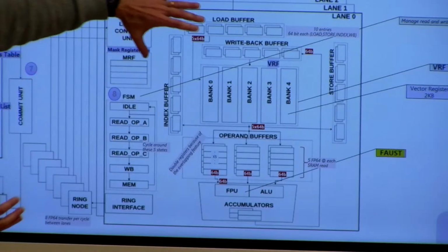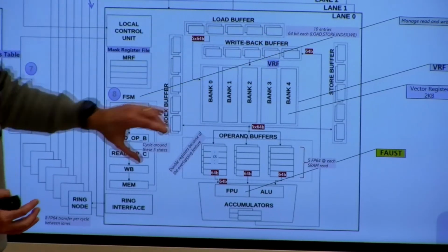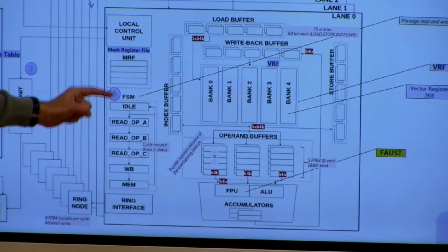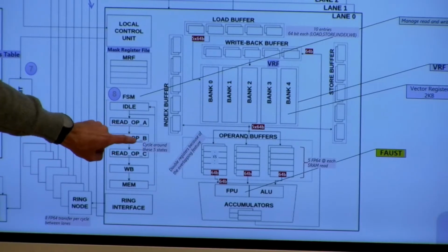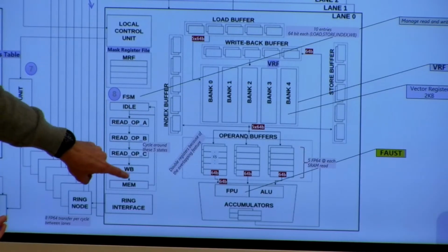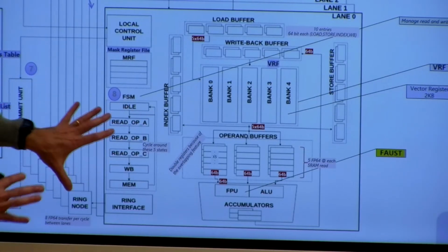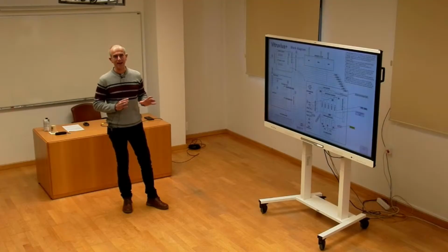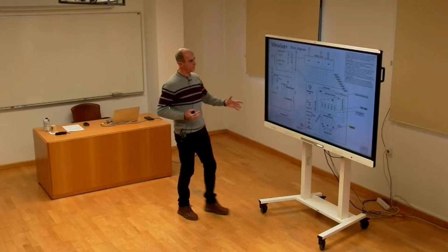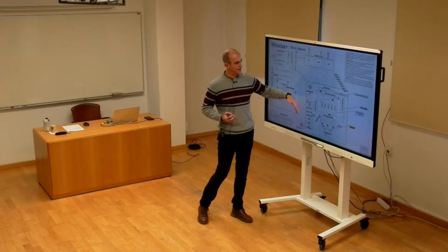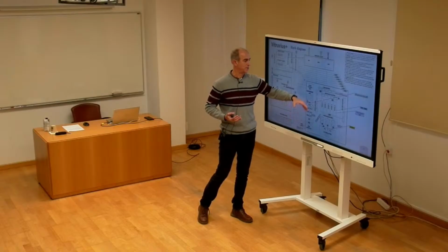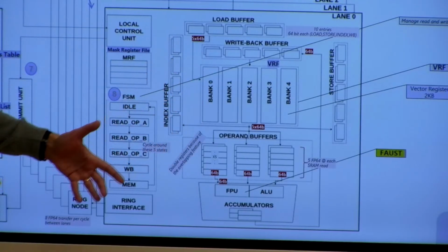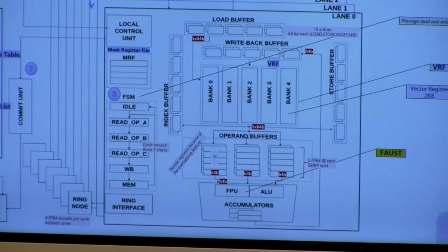But I can say this choice of 5 banks is strictly related to the FSM, because the FSM cycles through 5 states. It was just to keep it simple, to not build a more complicated arbiter. Usually now you generate hardware with some arbiter which takes data from the banks in a different way, not just with a simple FSM.